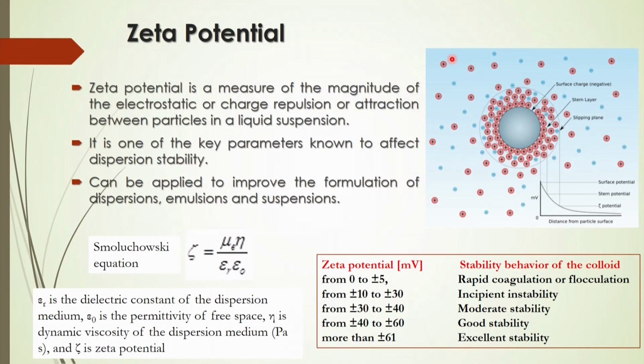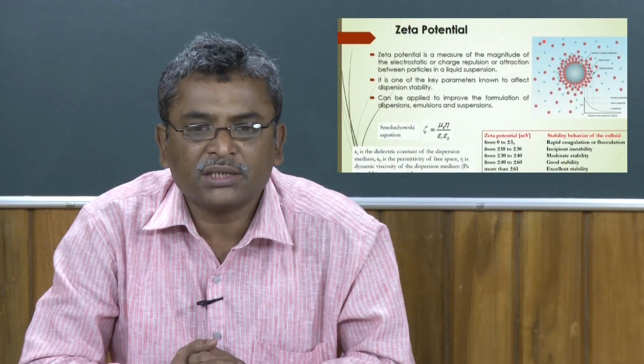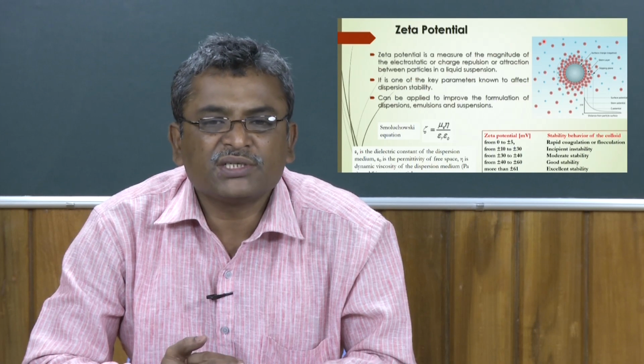And this is of course important, because the stability of the solid particles inside the bed for liquid-solid or solid-liquid-gas operation is very important, because you have to stabilize the system in a fluidized bed for stability, for better, uniform dispersion with stability. You have to know this Zeta potential, and whether these particles will attract other particles or not, whether it will cause coagulation, or make bigger particles by conjugating with negative charge particles or other charged particles. That depends on the zeta potential.